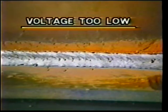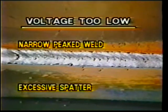A noisy, crackling arc sound is the result of low voltage. With low voltage, the wire is driven into the weld, disturbing the puddle and causing spatter. The weld bead will be narrow and convex in shape. Smoke levels will be reduced as the voltage is decreased. Notice the decrease in bead width and resultant increase in spatter.